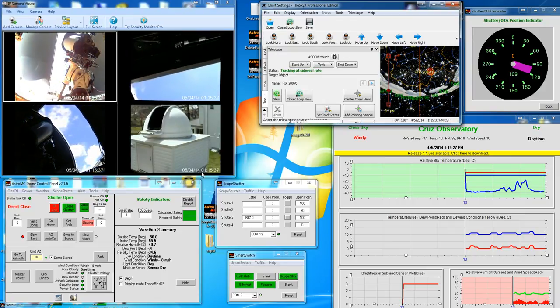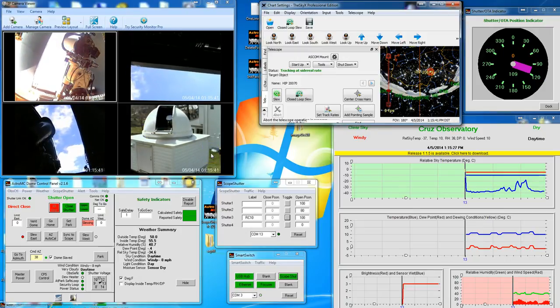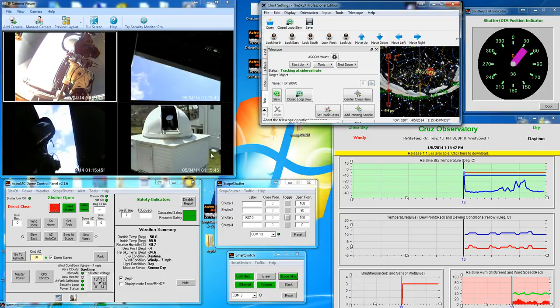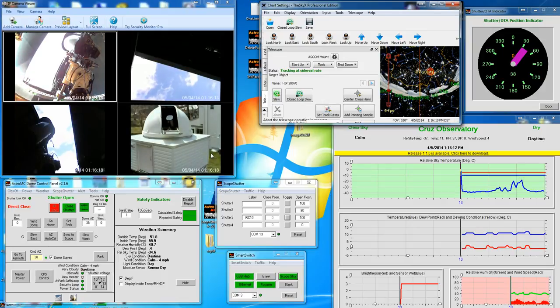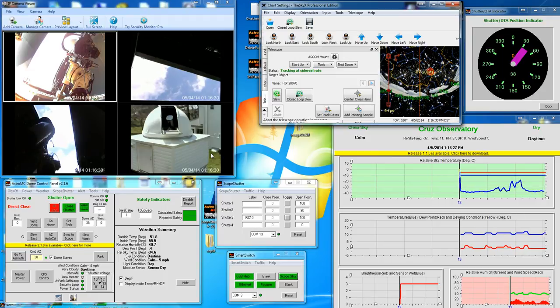Just a caveat, if you like what you're seeing here, be careful with these outside cameras. As I found out the hard way, these outside low-level cameras, although very inexpensive, you can pick them up for sub $100, considerably below $100, some models can toggle the infrared emitters that they use for lighting the low-level light. You can turn them on and off, and that's important with astronomy, as I found out. The first camera I had, the emitters were fixed on, and it flooded the entire area with infrared, which the CCD detector did a wonderful job of detecting as background light. So just make sure you buy the right one and you're able to turn those emitters off at night and still have the ability to turn them back on when you would like to use them.